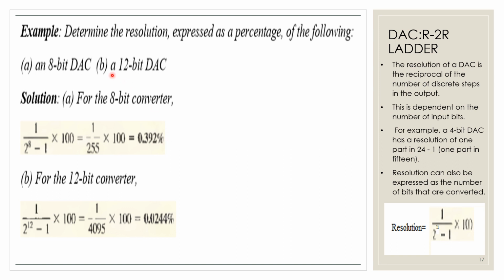Now in the second question it is asked for finding the resolution for input bits equal to 12. Then 1/(2^12 - 1), that's equal to 0.0244%.